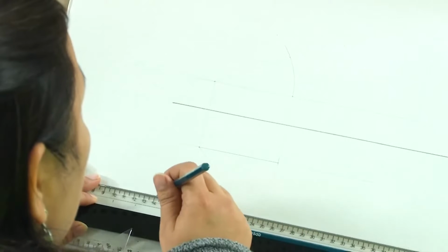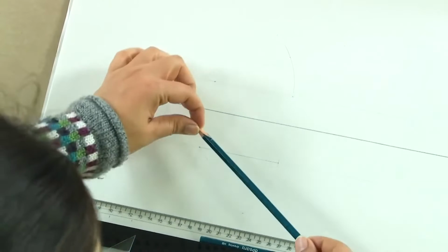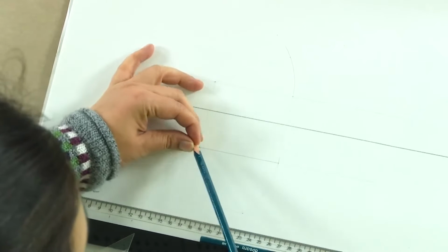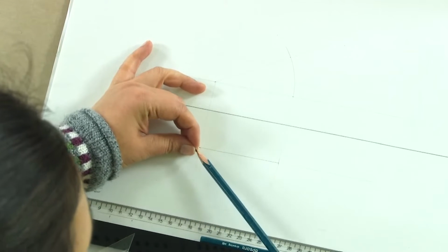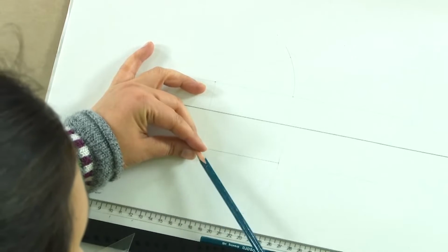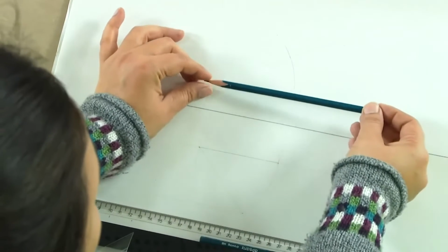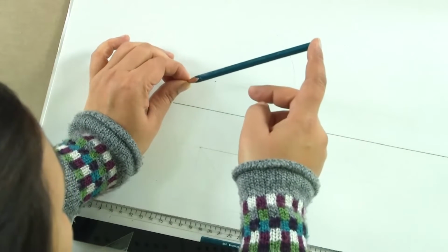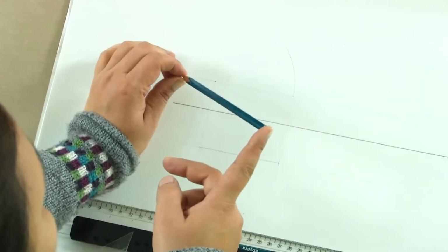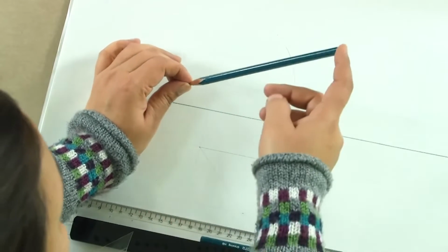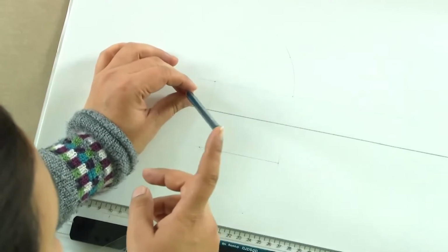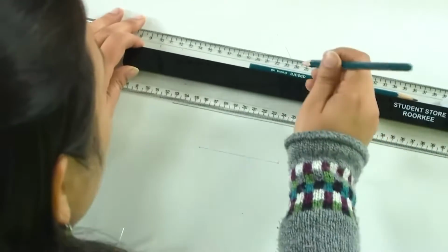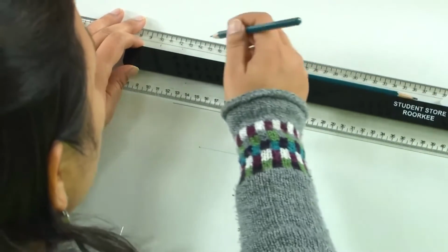Now, if you remember, when I was explaining to you the movement of the line, we said that if it is inclined to one plane and it is inclined to the other plane as well, this is how, in a conical manner, the line will move. And similarly, if it was inclined to, say, HP at an angle of 30 degrees, to make it at an angle of, say, 45 degrees with VP, we will have to incline it in a conical manner such that the top point maintains its distance from the horizontal plane and the vertical plane.